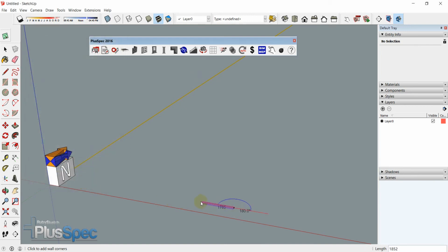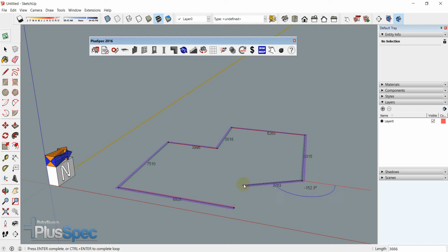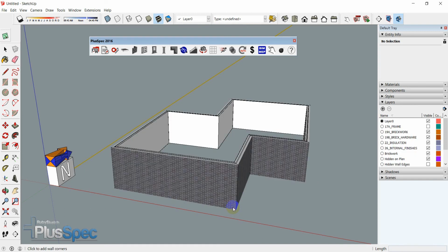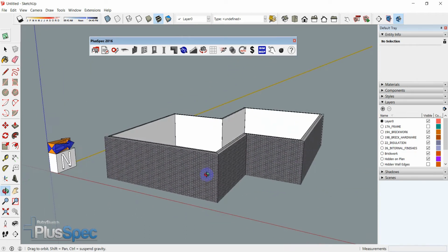Okay. So essentially we haven't got anything to trace over. So really all we're doing is just drawing a house from scratch. And we can make it any size we want to, and any type of house that we want to. Notice that see it snaps to that line there? That means that it's square. So if I looked at it top down, on an axis, that's right, yep. Okay, and I go back to here. Now this is the one that we probably want to know a little bit more about. If I want it to line up with here, I really need to push shift when it's on the axis. Right, so I'm going to push shift, and I'll just hold my mouse to the end here, and you'll notice it's kind of snapped to it. Right, and I clicked, right, and now I have, I guess, what would be considered a ground floor.